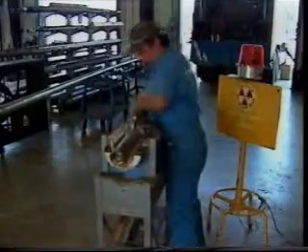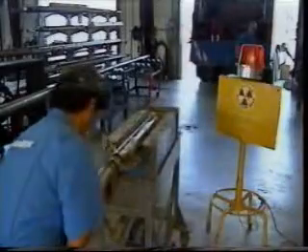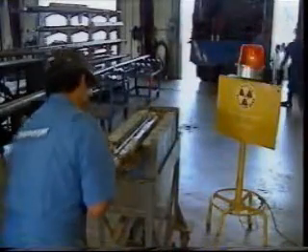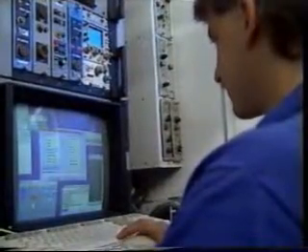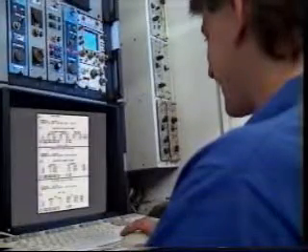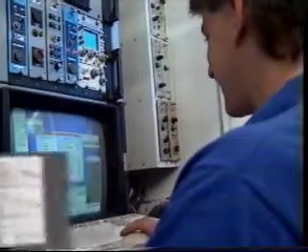Service companies utilize an aluminum block for periodic master calibrations. The tool is placed in the block and a reading is taken. Certain count rates are recorded and can be reproduced at the well site. Further tests can be made by the insertion of different types of materials to alter the count rates. At the well site, field calibrators are utilized to make a check of these tools prior to logging. As usual, these records become a permanent part of the survey.